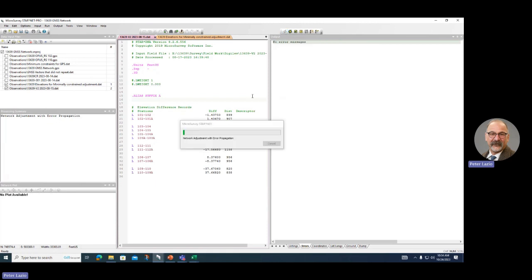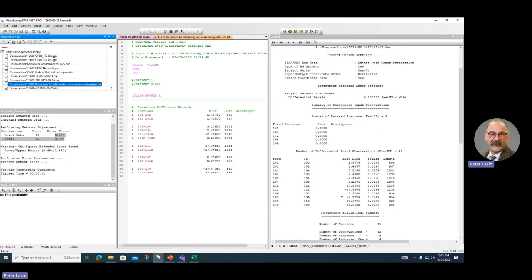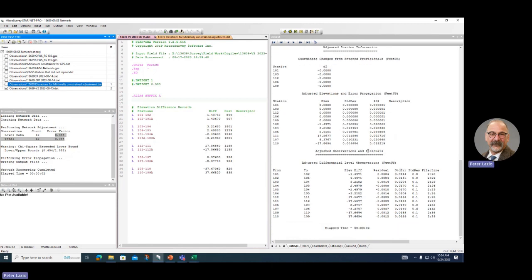It'd be nice to be able to do them all. So we're way, way, way better than what we expected. So 0.084. Now, so, okay, my leveling I know is good. Look at my residuals. I mean, my residuals are 4,000s, 4,000, or 10,000s, 14,000s. So now I'm going to combine everything into one adjustment. Now, I don't want my minimum constraints in there. That's the nice beauty of being able to click that out. I don't want my elevation minimum constraint.